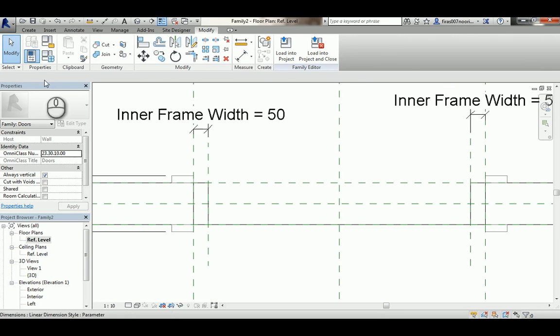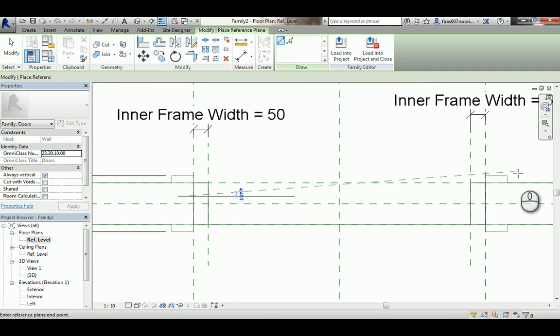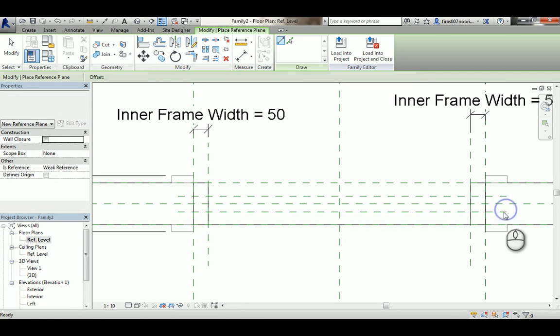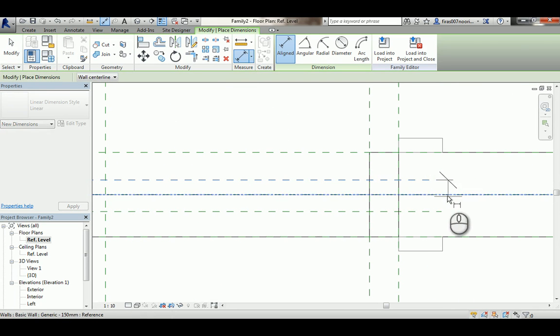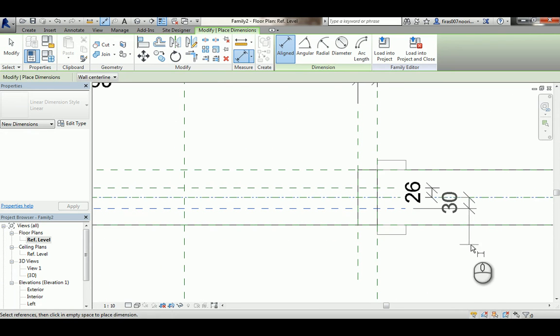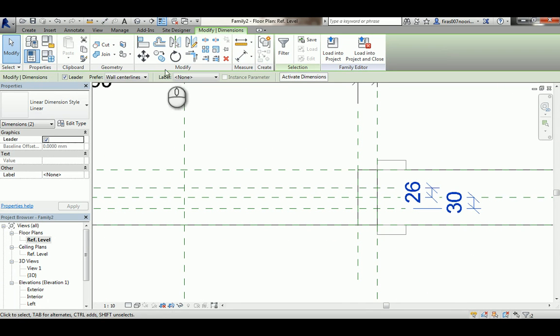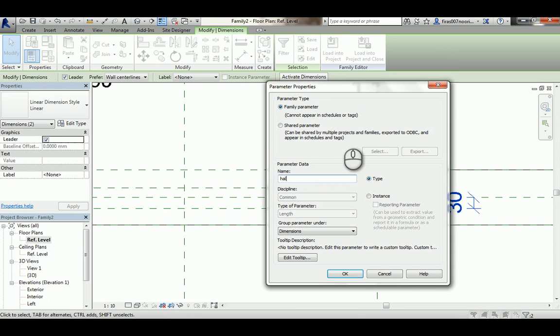Anyway, now let's create the door leaf itself. I'm going to create another one here, DI again, from the new one to the original here, and from the new one to the original here. Select both, and then add a parameter, let's call it half.